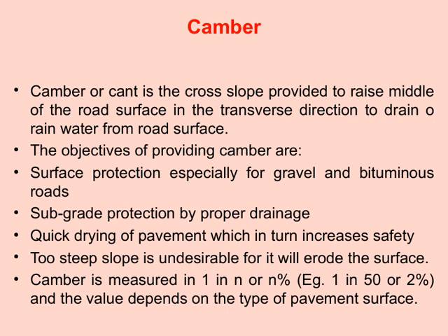However, it's important to strike the right balance. If the slope is too steep, it can cause erosion of the surface, which we definitely want to avoid. That's why camber is carefully measured, usually expressed as a ratio like 1 in 50 or a percentage such as 2%. And of course, the specific value depends on the type of pavement surface and the expected drainage needs. In essence, camber is a simple but crucial feature of road design that plays a significant role in maintaining the durability and safety of our roads.